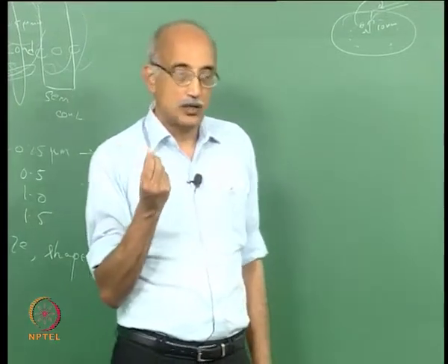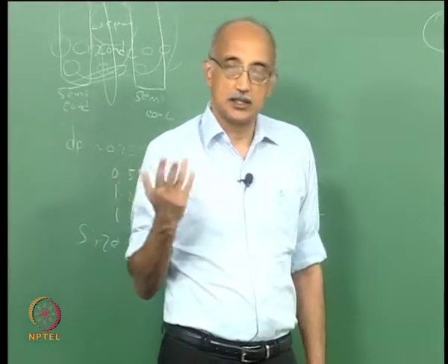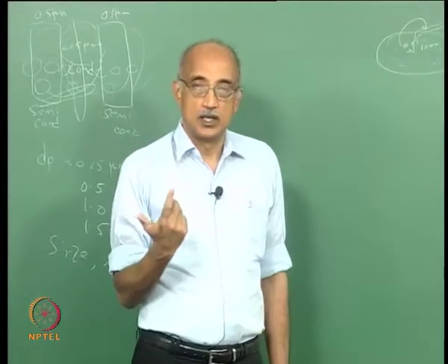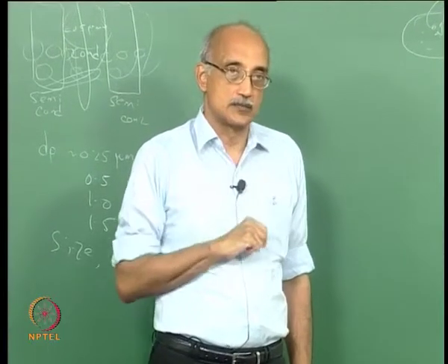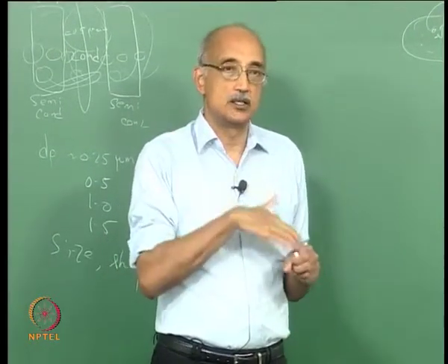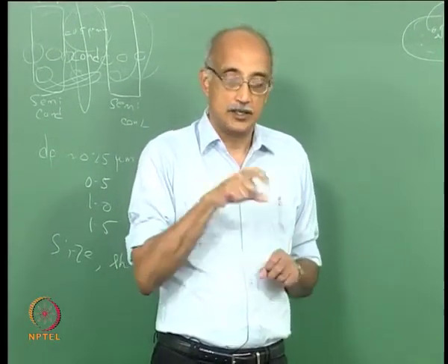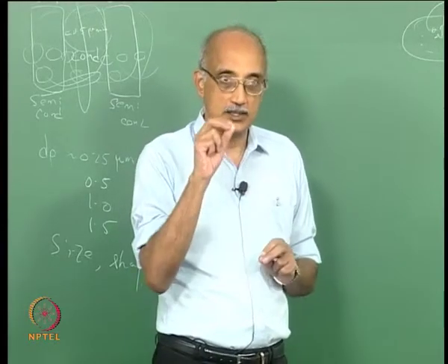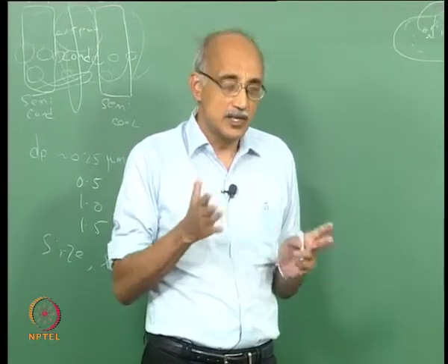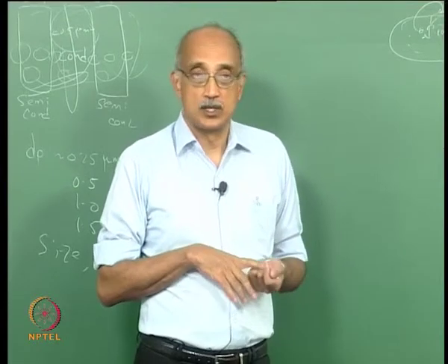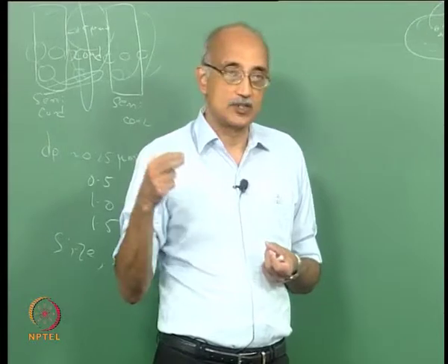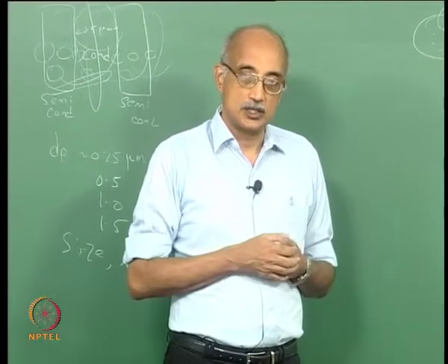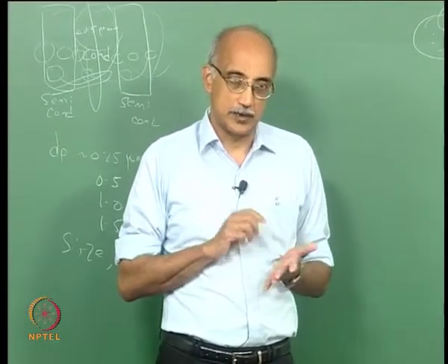So if you have a particle that's 10 microns in size and it gets caught in this airflow, it's going to fly around inside this enclosure with very high velocities. So it can actually go and physically impact on the disk and dig a little hole in it. It literally digs a crater. So that mechanism is called ballistic damage. And that happens primarily because of larger particles which have sufficient kinetic energy and momentum to cause this type of failure mechanism to occur.